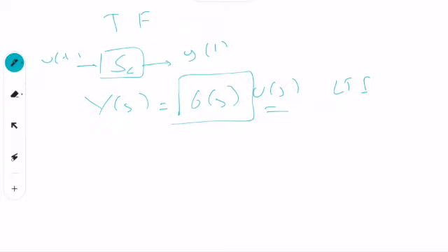So transfer functions are inherently limited to linear time invariant systems. No nonlinear component, no time variant component. There are specific operators, special operators, which are also called transfer functions, but they're not exact transfer functions, to model time variant systems. But it is a very different topic. So if I give you a transfer function, and I say that it's a transfer function between input and output, you can automatically say that your system is linear time invariant.